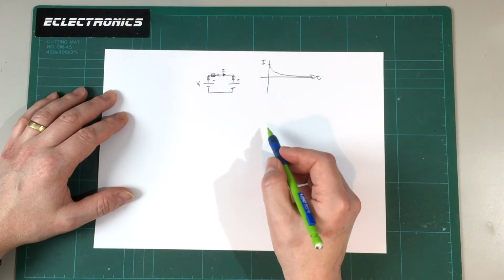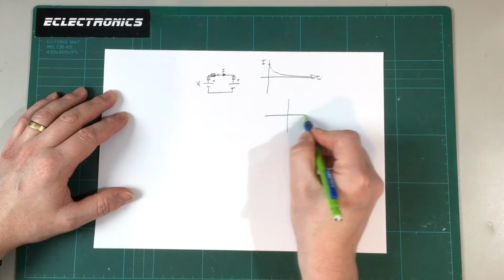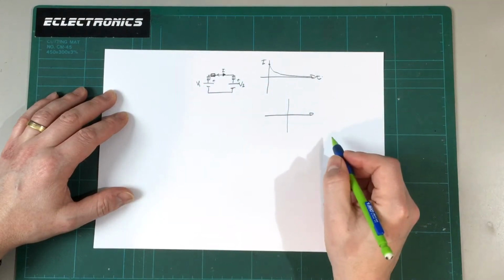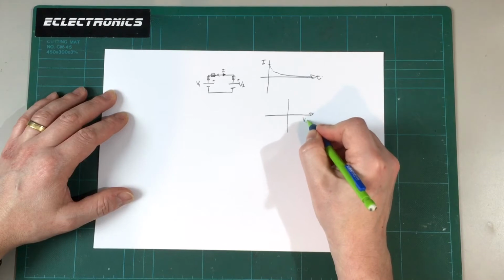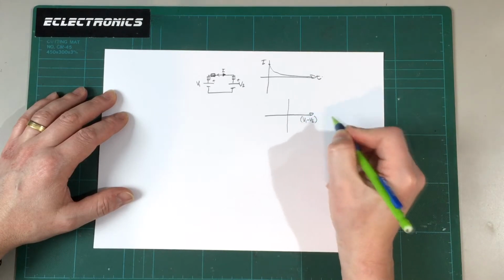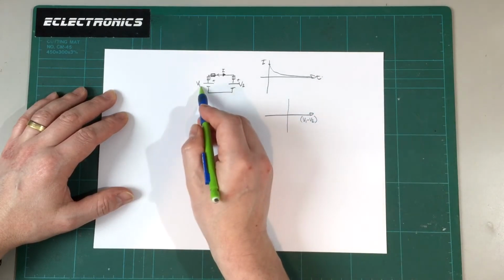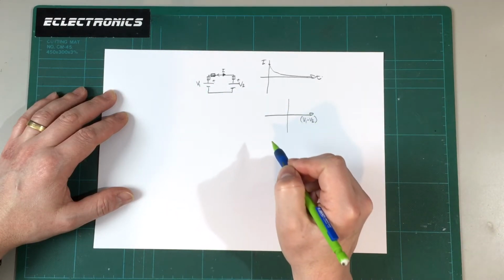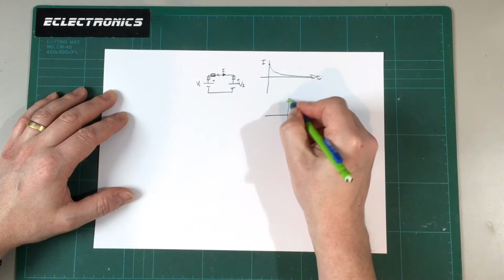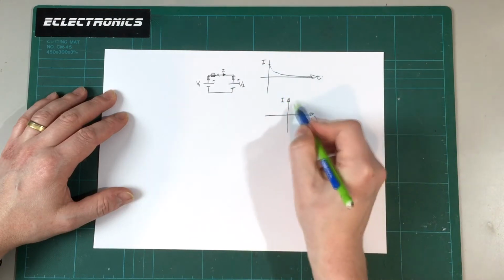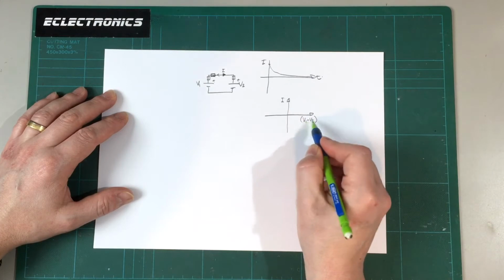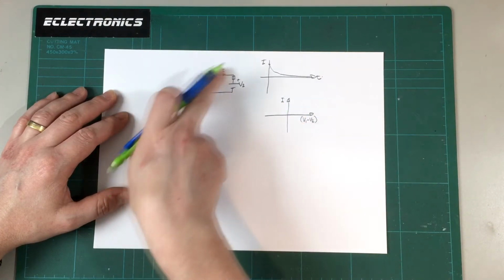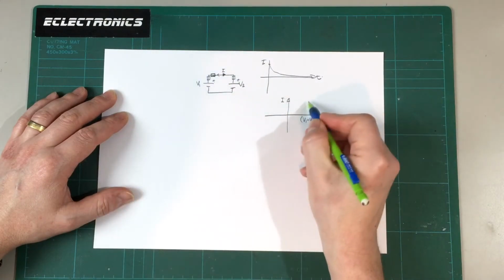So if we plotted, let's say this cell is V2, this cell is V1 in terms of voltage. If we plotted V1 minus V2, so the difference in cell voltages, where V1 if positive puts us on this side of the chart, then I would flow in that direction. So with I defined that way, we'd be in this quadrant up here. So if V1 is greater than V2, that I would be positive. Charge would be going from cell 1 round to cell 2. So we'd have something in this quadrant.